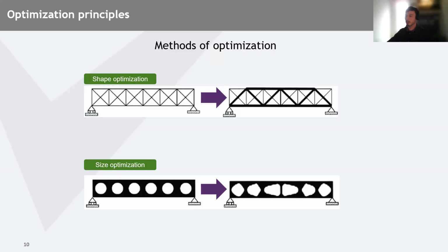So that our shape is already fixed. We know the best shape of our structure, the global geometry, and then we can optimize the members, the plates, the welds themselves. So this involves our structural elements achieving the desired performance criteria, such as weight, for example, but obviously we have to maintain the strength. So we need to find the perfect spot.